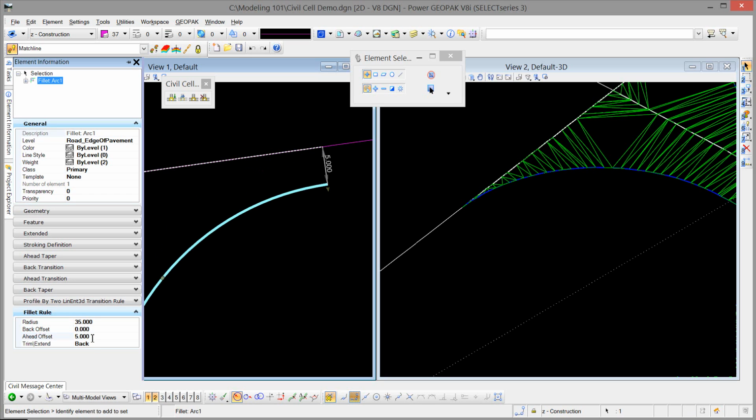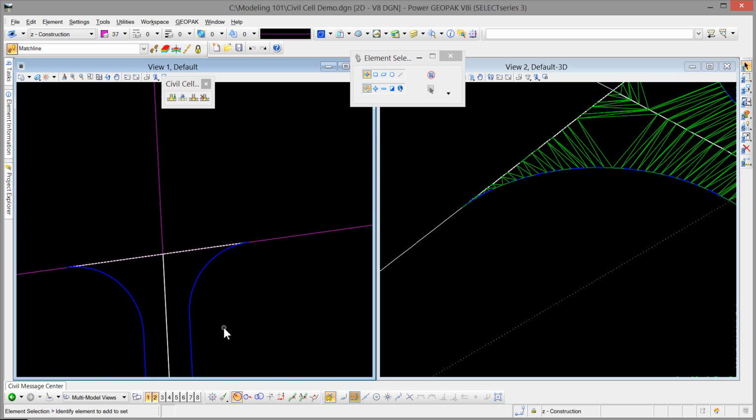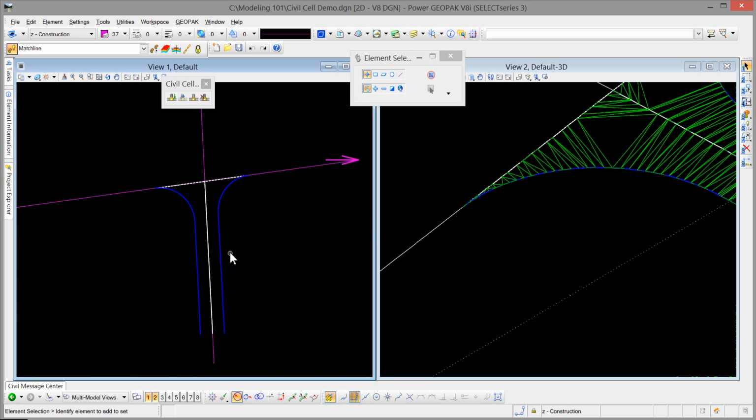It still thinks it's closed, but what I have seen people do sometimes, if they get a bleed right here, they'll change that to like 0.01. You can't see it, but it makes the terrain fix itself. Okay? And so just keep that in the back of your mind if you ever see that happening. But if you construct it the way that I did, and this match line is snapped to that end of that fillet, it shouldn't ever leak. The triangle should never leak, okay? So we got our break line in, we got all of our terrain done.